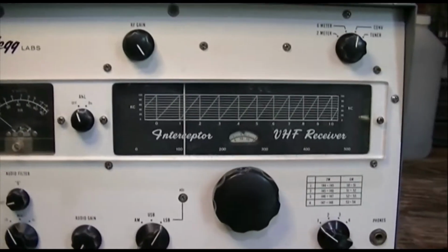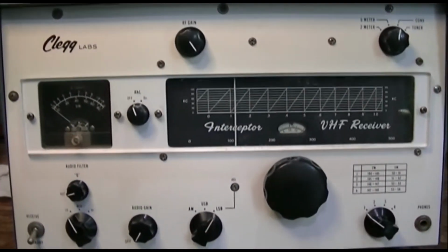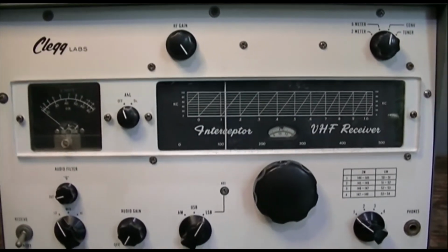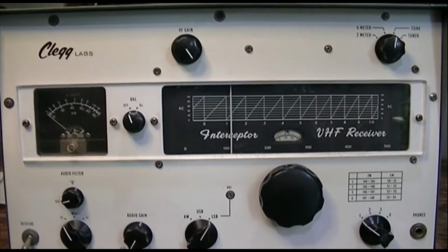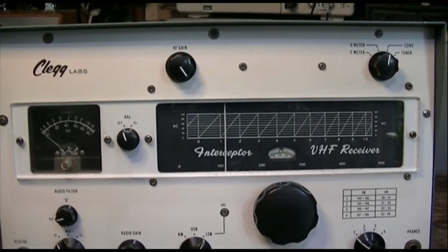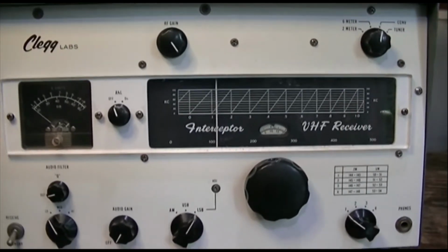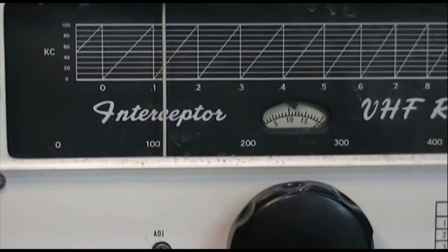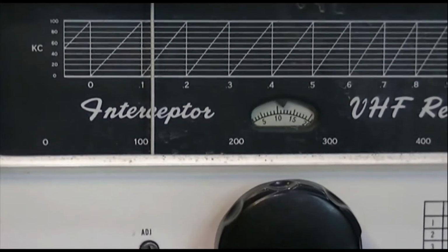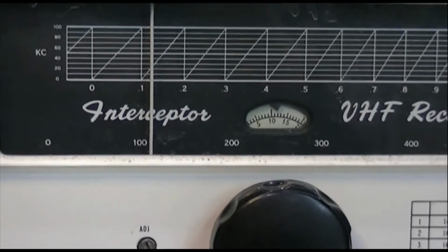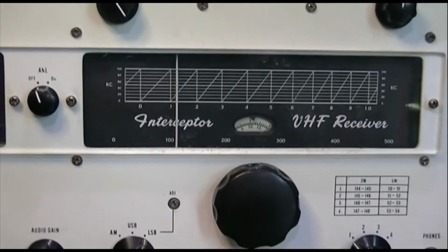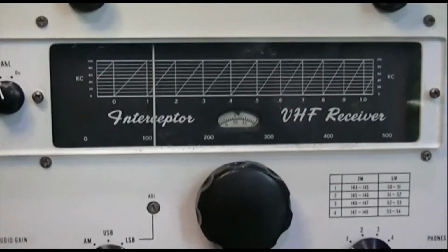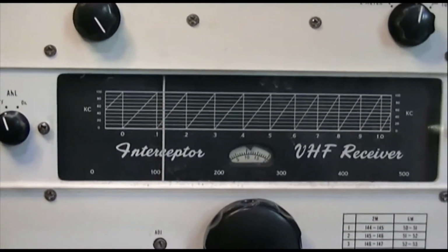It certainly is a shame that this receiver doesn't have a linear master oscillator like a Collins or an SB or Hot Water Series Heathkit, or the latter day FT Series Yaesus or Kenwoods. Actually, those have coil and capacitor VFOs, but they have much better dials. And this radio certainly could have benefited from a dial with a 1 or 2 kc readout, and it is linear enough and accurate enough that it could have had one.